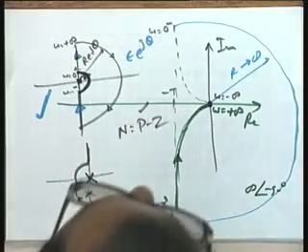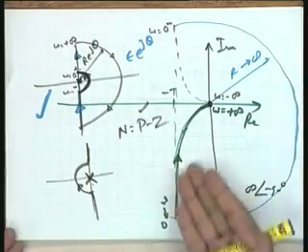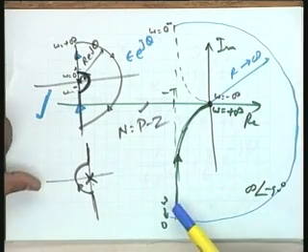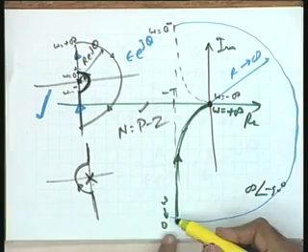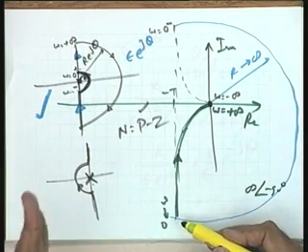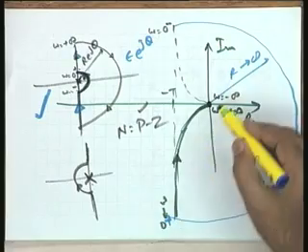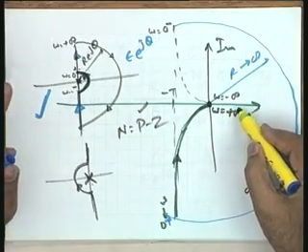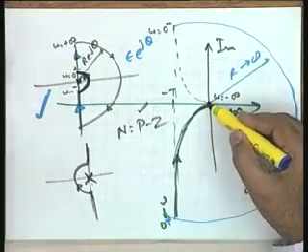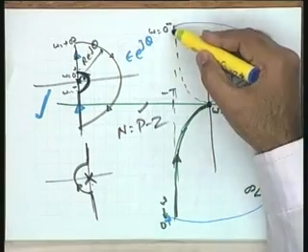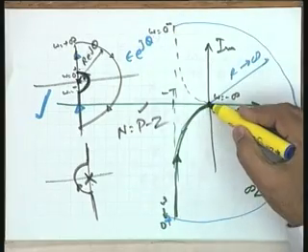It's the basic understanding, you see. As far as Nyquist stability is concerned, you will quickly get this information from the polar plot itself. You see that detouring of the origin, which you have taken because of the pole at s is equal to 0, has resulted in this particular plot. In the polar plot you started with omega is equal to 0 plus. It's the frequency response of the system, and you went up to omega is equal to plus infinity. This is the experimental data, or the data obtained from the open loop model. Omega from minus infinity to 0 minus is a mirror image.